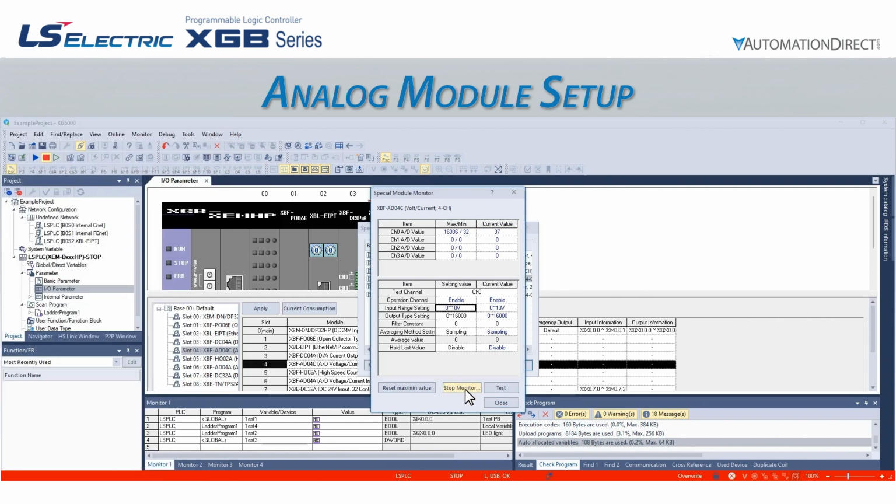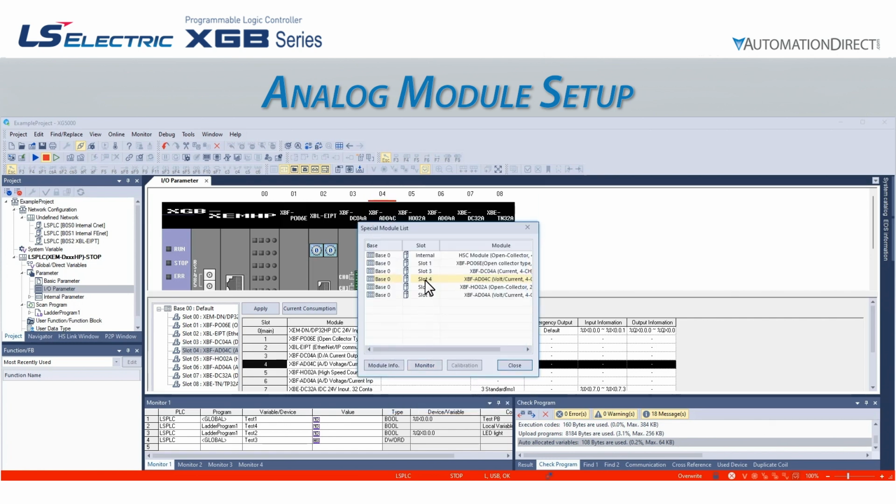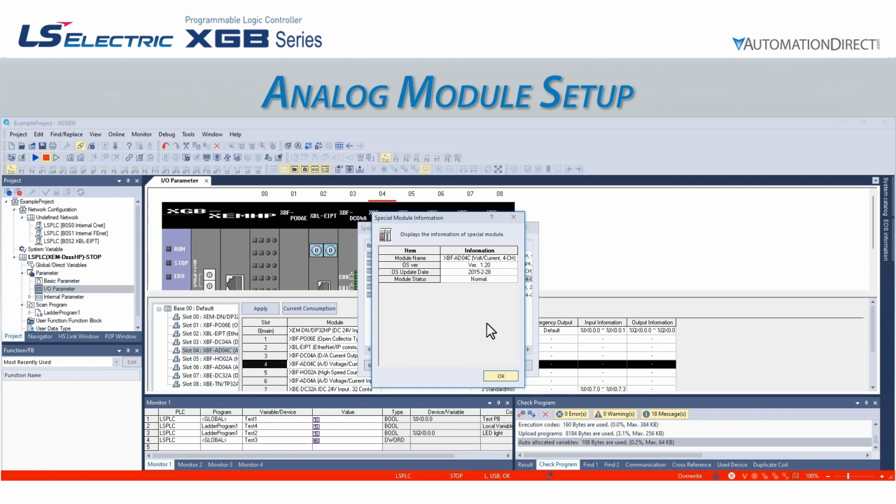Below this, it will allow us to select a specific channel and then test our channel configuration. This is very useful for initial setup and testing of an analog input once connected to its field device. Please note this testing can only occur if the CPU is in stop mode. If you are in run mode, the test button will be grayed out. We can also view module information from this screen. Instead of clicking the monitor button for a specific slot, we would instead click Module Info. This brings up information about the module, including firmware revision, module status, and more.